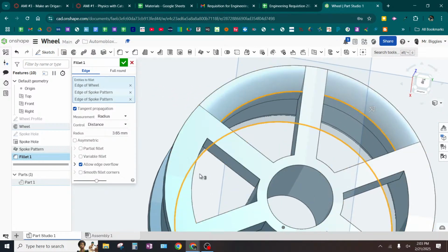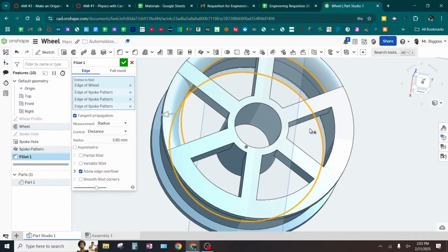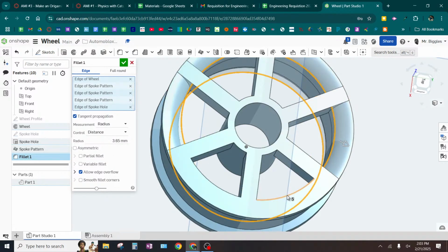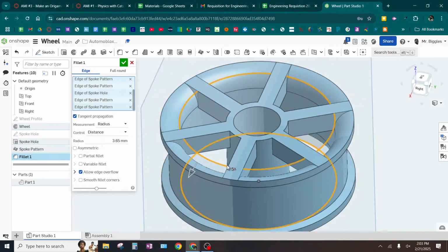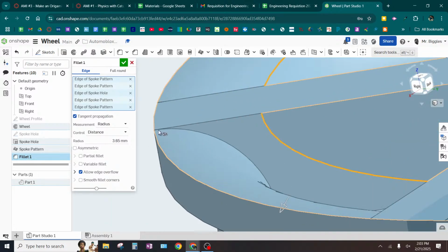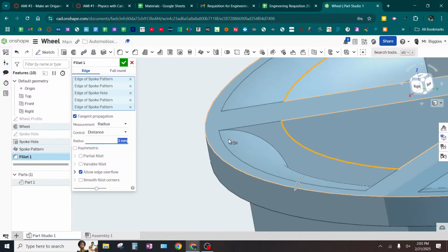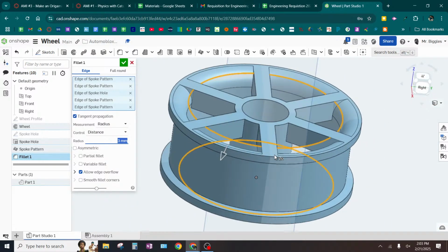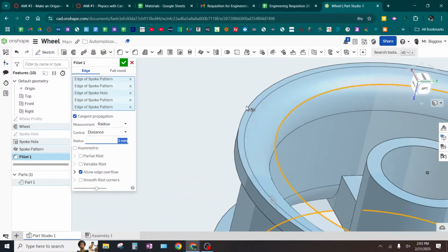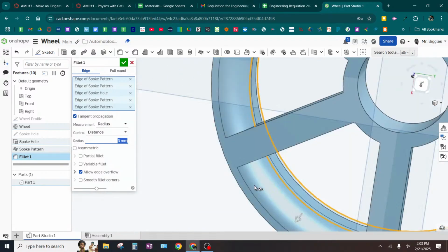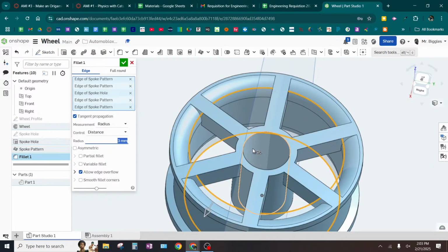If you don't like this look, okay, realistically, I highly doubt that the fillet actually goes all the way to the very edge. It probably flattens out a little bit before it gets to the very edge. So you can make this radius smaller, like I could do just 3, for example, and that kind of brings it in some. Kind of hard to measure that with calipers, but you notice it kind of has a little bit of flat lip first, okay? So I have filleted that. Well, that's a pretty good fillet. So I'm done.